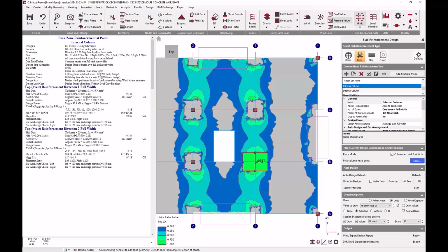And then what is the process to get the reinforcing layouts and bending schedules? So the concrete column, beam and pad modules all do bar schedules, but the concrete slab and wall designer will produce design intent drawings as opposed to detailed bar scheduling drawings. But we can have a wee look at that as well if we've got time.